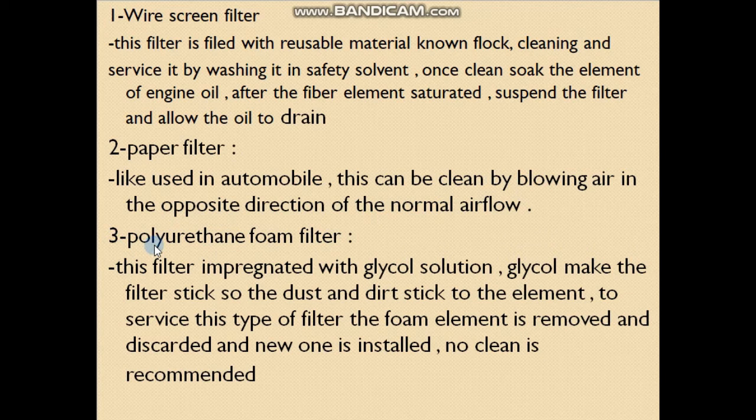The last filter is the polyurethane foam filter. This filter is impregnated with a glycol solution. The glycol solution makes the filter sticky so the dust in the air sticks to the element. To service this type of filter, the foam element is removed and discarded and a new one is installed. So no cleaning is recommended.